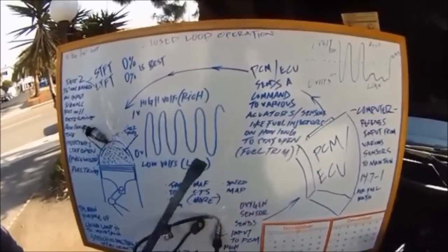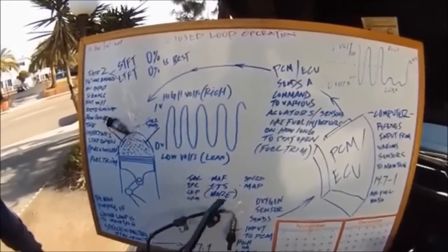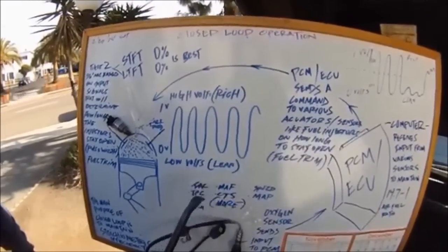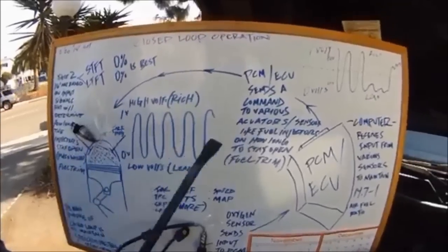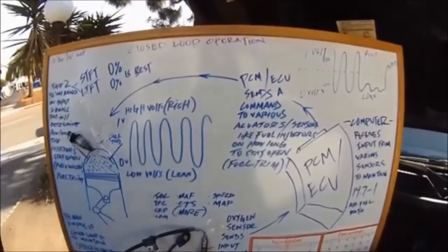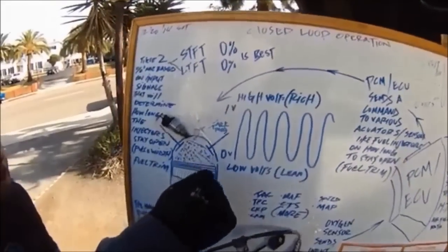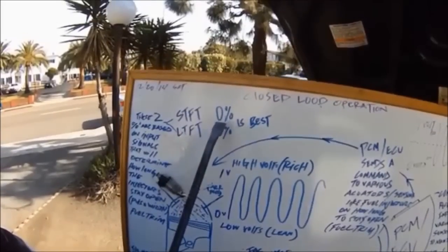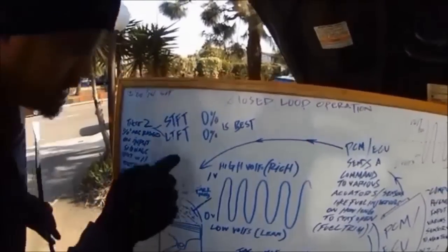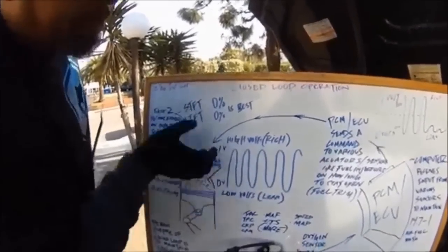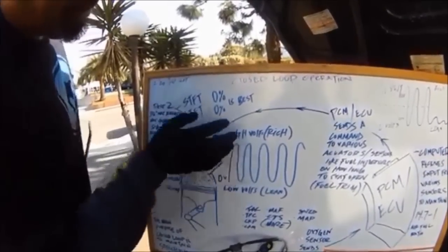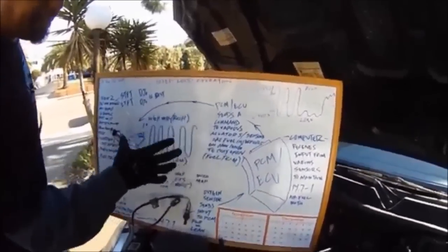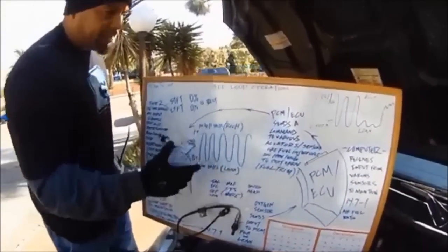If you have a check engine light like the cars I showed you, and it's one of these, it doesn't matter, you're going to fail the smog anyways. They won't even smog the car. But if it's one of these that are related to the emissions test, you're going to fail definitely, because one of these will affect this fuel trim. The fuel trim that you're looking for, you want it at 0%. Why? Because 0% is saying that the computer doesn't have to adjust much or anything at all. It's always adjusting, but just say that it stays at 0. The computer is always adjusting the fuel trim constantly, in milliseconds, fractions of a second.